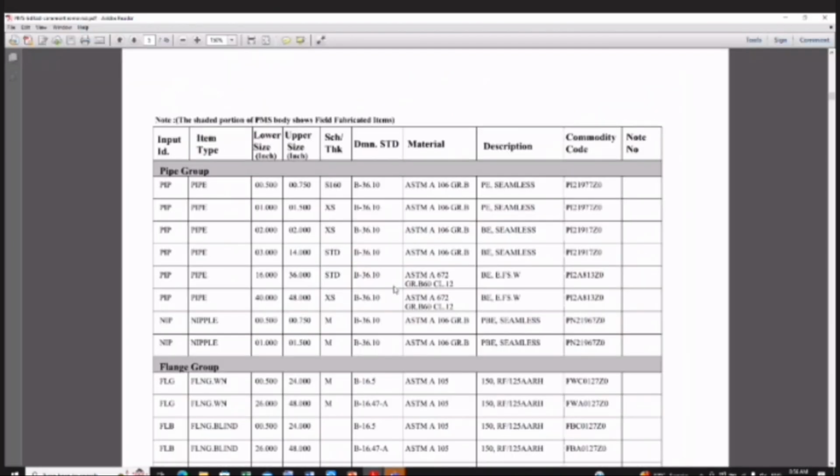So this is just a designation or some name is given to that material, because when you go to vendor and ask, you can ask, I want carbon steel pipe. You will specifically tell them, okay, this is the type, this is how it is called. So for each type, there are some namings given by ASTM committee. For metal is A, non-ferrous is B. That we will see later on.